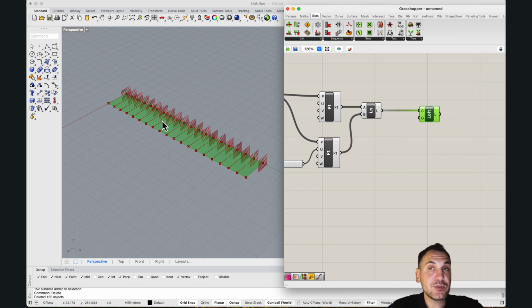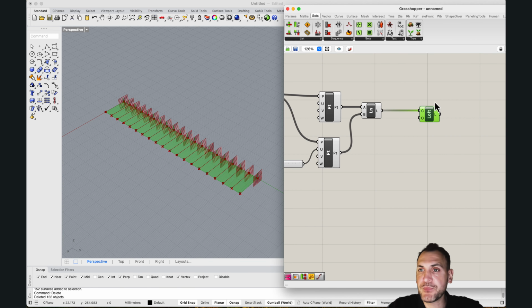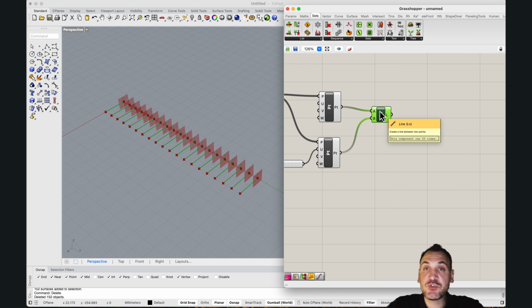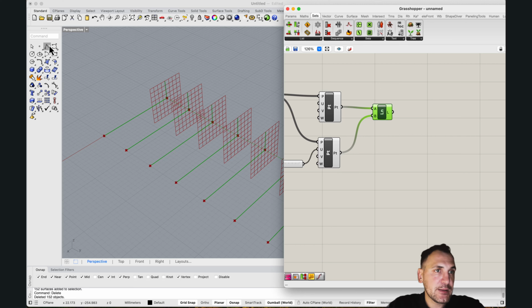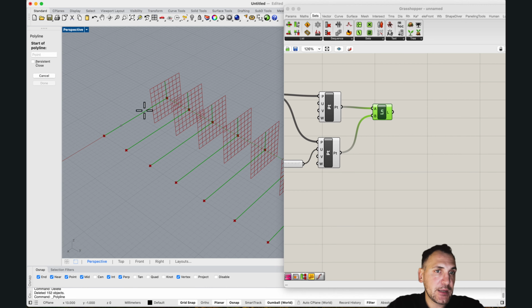But if we were to twist it, then it can create non-flat construction geometry. So these might start distorting a bit because of the loft operation. So instead of doing loft, I'm actually going to do triangles. So how do we build the triangles? One way of thinking about this exercise would be, how do we connect these lines, right? So let me bake it first.